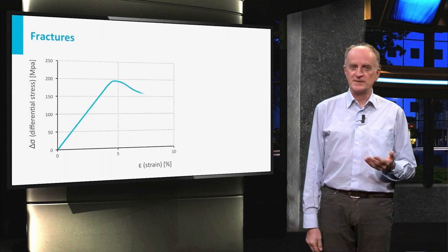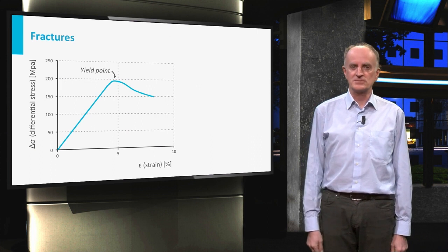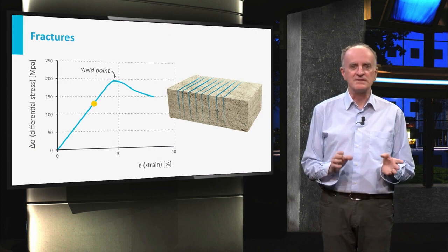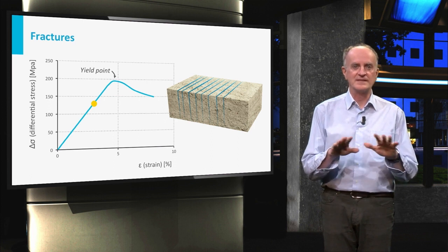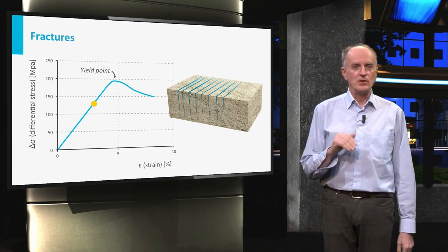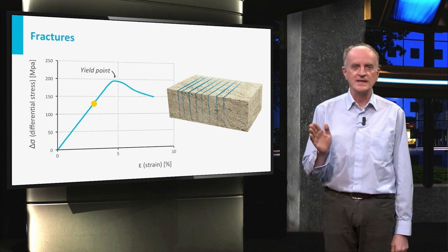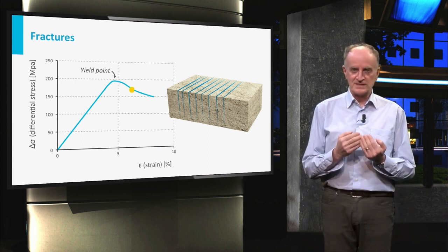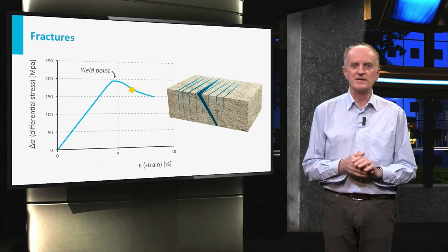Remember the stress-strain curve we discussed during the first clip? Looking at deformation structures, we distinguish two stages. In the first stage, deformation is low, typically less than 5 to 10%, and fractures progressively form distributed over the entire rock. Despite the low deformation, this stage is very important because fractures are numerous and have a major impact on rock properties. With increasing loading, the rock will eventually fail, developing a mechanical instability and forming either a fault like the one shown in the picture or a fold.